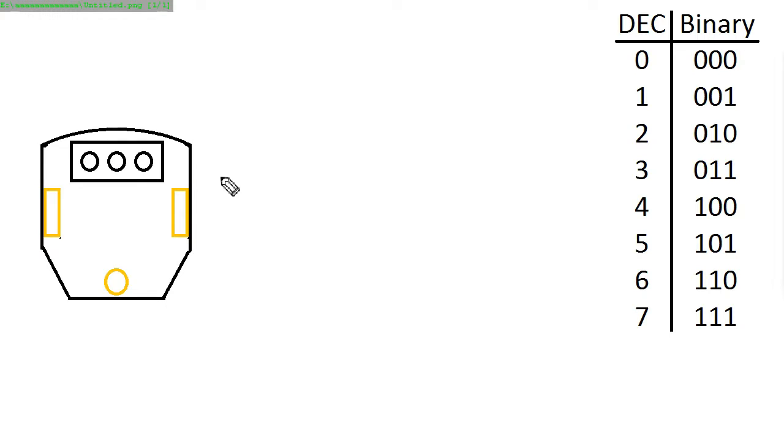So instead of doing a lot of if-then statements to test for every possibility, I decided to do a once-off scan of the line sensor and take all those possible readings and represent them as a binary number, and use that binary number in my program directly. So the way I did it was I would scan the line sensor once and see, do we have one line, two line, or even three line? And I would say, okay,